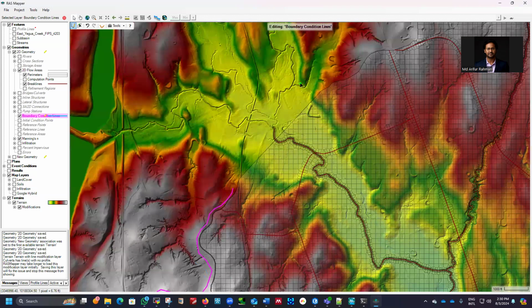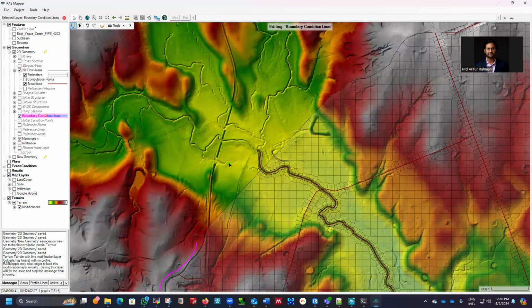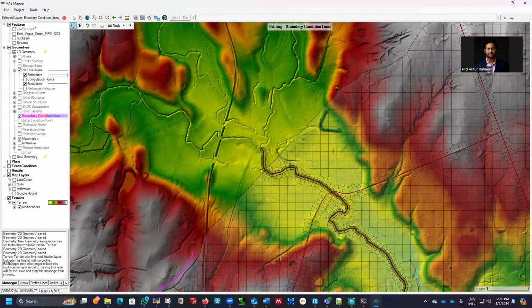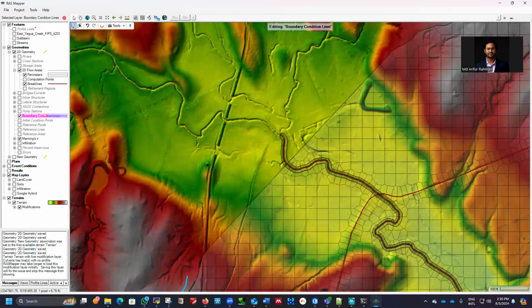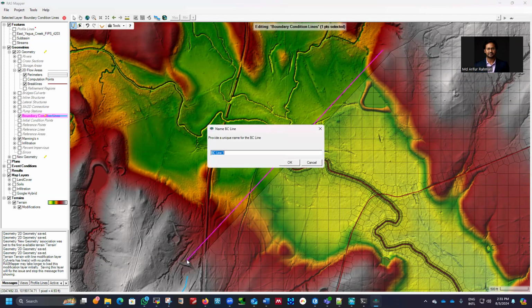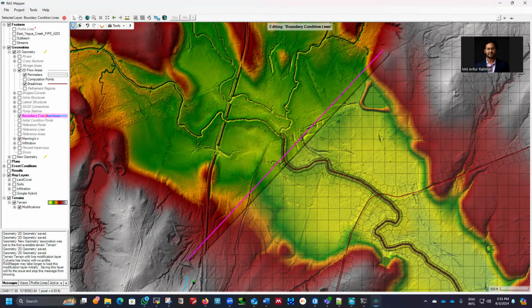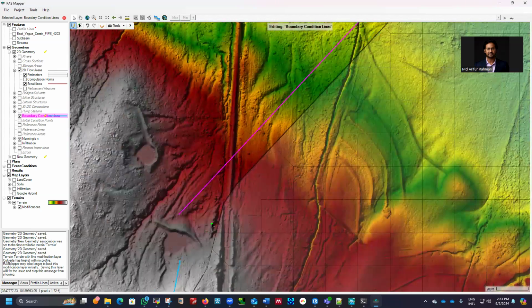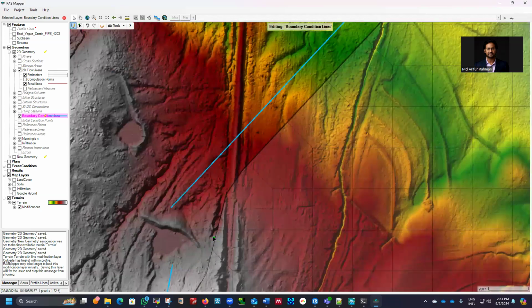So we have this boundary, then just draw the same way from left to right. That's the left bank, that's the right bank for inflow. So we can just draw the line starting from here, and I can just end the boundary all the way to this location, and you see this is inflow. Inflow BC, we have only one inflow, so we can just use inflow BC and make sure that we have different cells. So this cell is basically missing. It doesn't have any boundary.